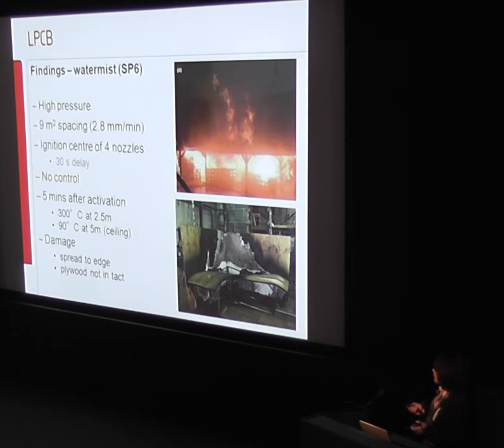So within the test, we introduced a 30-second delay, which ensured there was enough heat to pop all four nozzles, and so it gave it the best chance to deliver water onto the fire load. In other tests, we did stop the water and wait a few minutes to try and pop some more heads, so that we could offer the water system enough time to deliver onto the fire load.